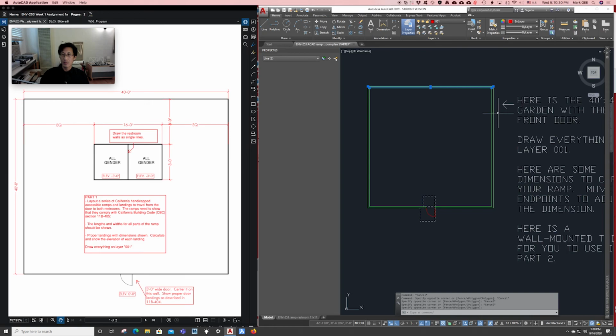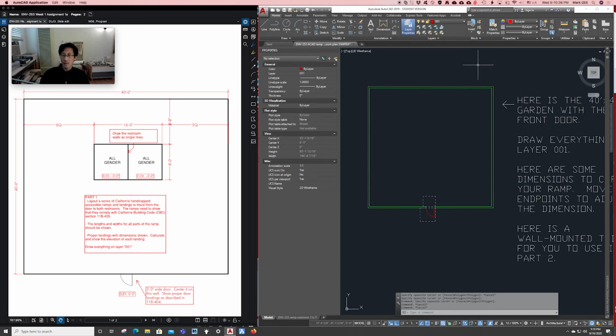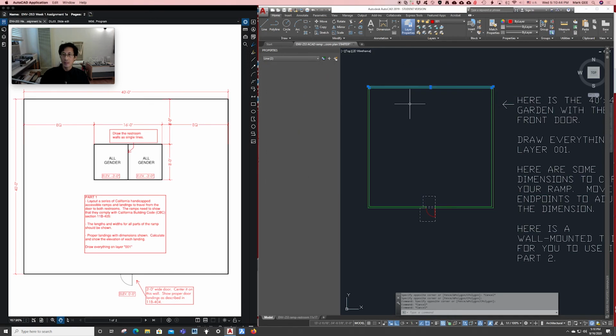All right, if I encompass something completely with the blue box, it selects it. The other is right to left. If I click someplace, release the mouse button and move the mouse across something, and then click after I've crossed something, it selects those things that I've crossed. With the right to left selection, I don't have to encompass the whole thing. Left to right, you have to encircle the whole thing. Right to left, you don't.